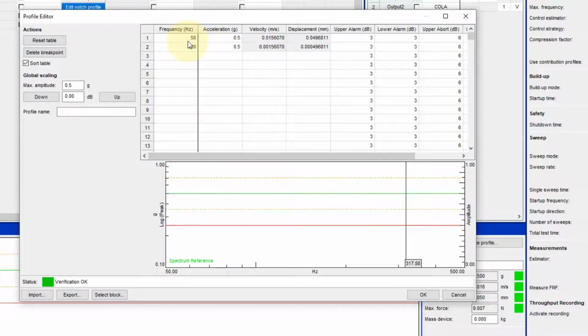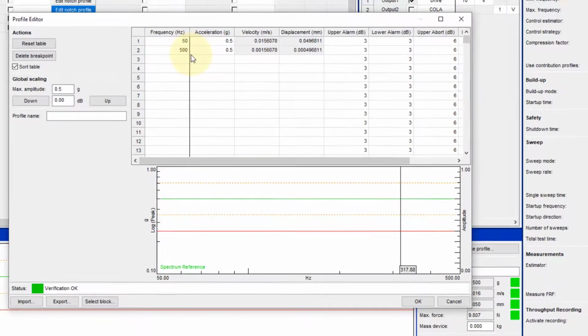For instance, you know the typical operational RPM of your jet engine in flight, so you're going to do a sweep from maybe 5 hertz or 10 hertz, whatever that low frequency of your shaker is, up to the operational speed of your jet engine.